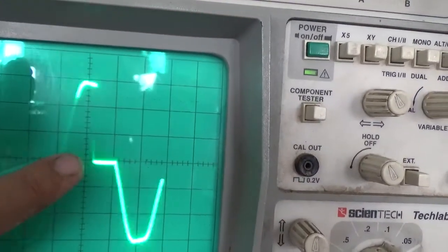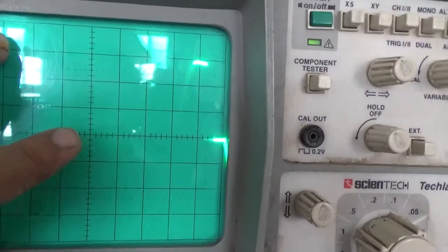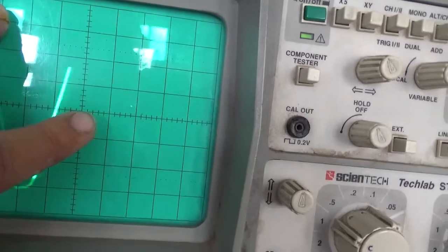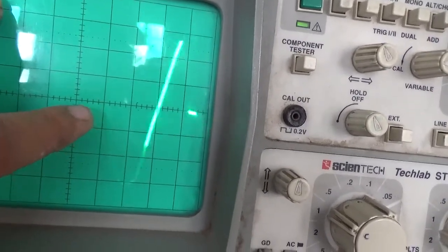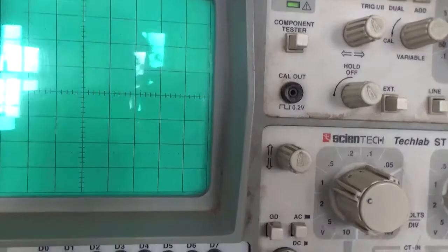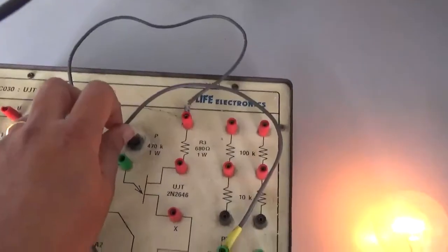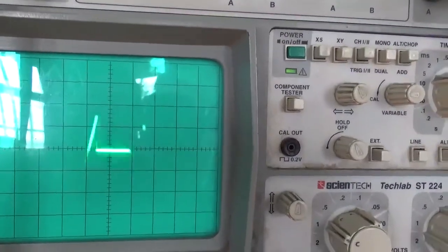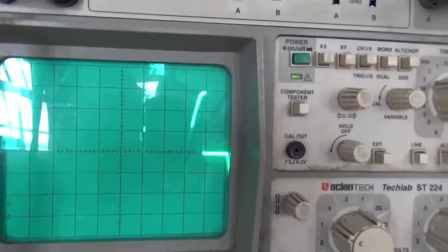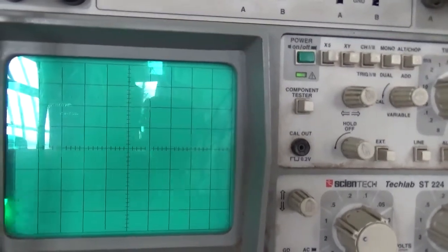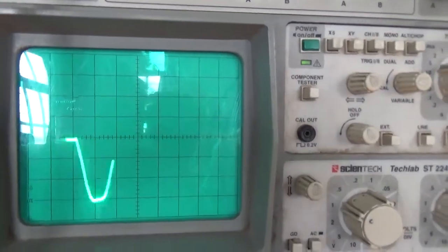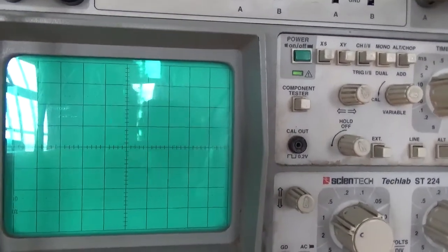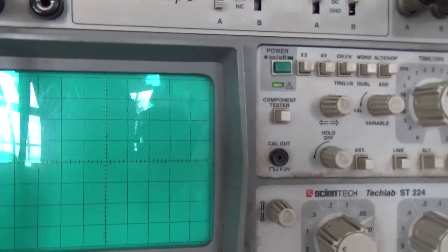What you can understand by looking at this waveform is, during this duration the SCR is in the off state. When the SCR is in the off state, voltage will appear across the SCR. At this point, I am going to give the firing pulse, so the SCR turns on and the voltage across the SCR goes to 0. Now as I vary this potentiometer knob, the alpha is varying. Until you give alpha, till that point the SCR is in the off state and voltage is appearing across the SCR. Once you give the firing angle, the voltage across the SCR goes to 0.